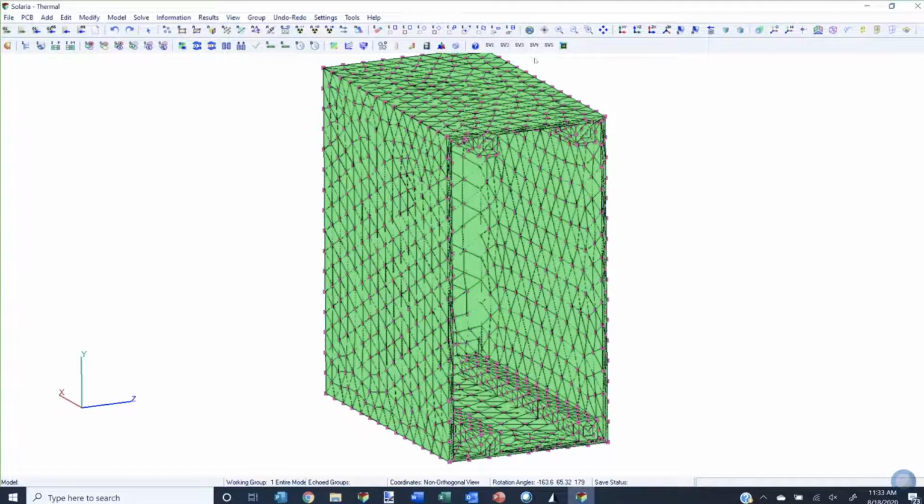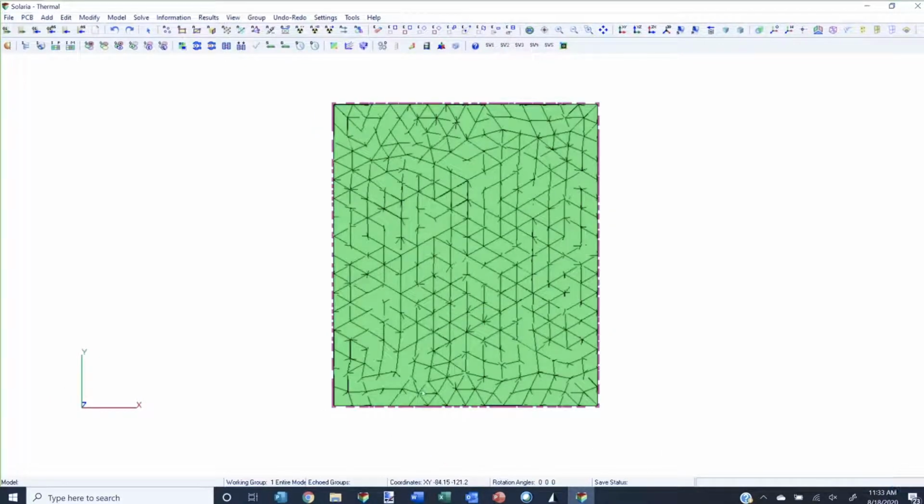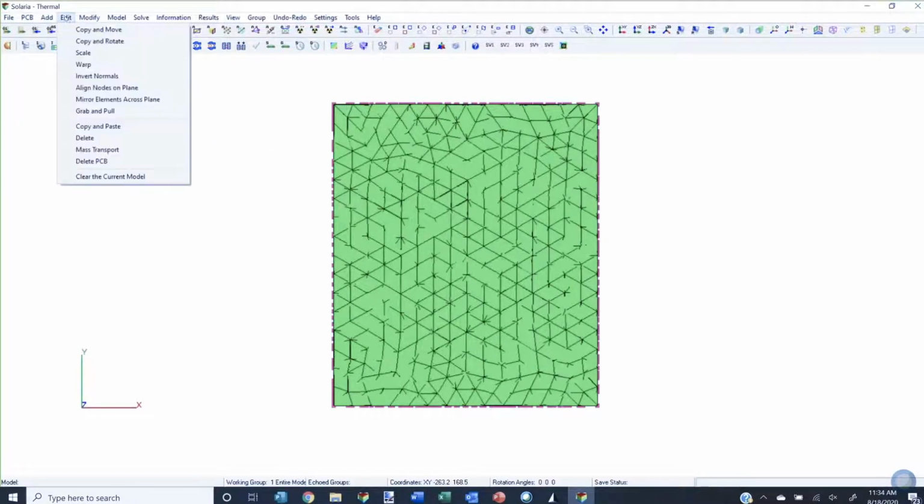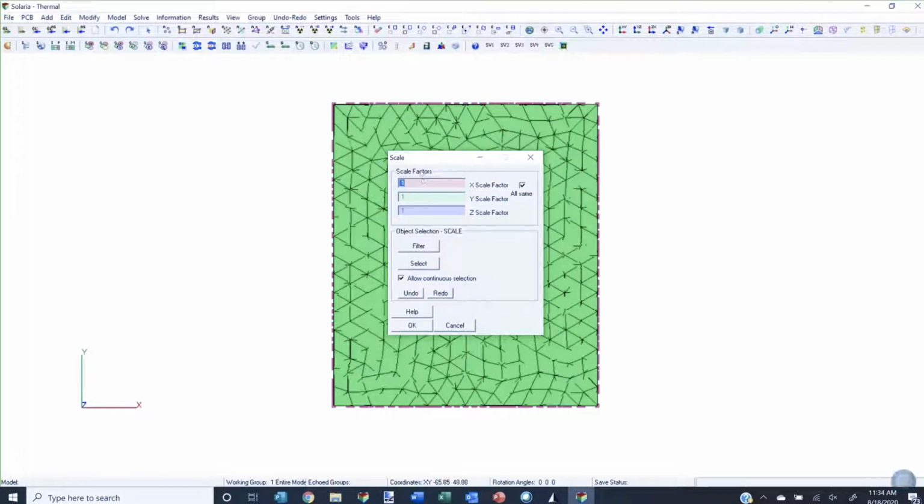Okay, so here it is. If I swing it around, I can turn on the mesh, and there's the exact model that was just created. Now, if I look at the XY view here, I'll notice down the bottom, when I move my mouse around, it tells me coordinates. And the coordinates are like 105, and down here it's a minus 115, okay? Which tells me the step file was in millimeters.